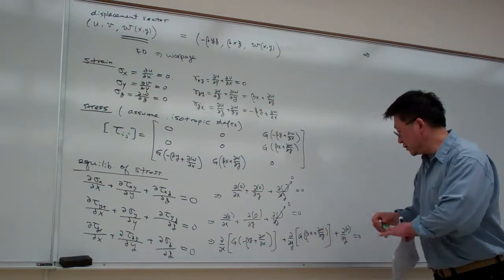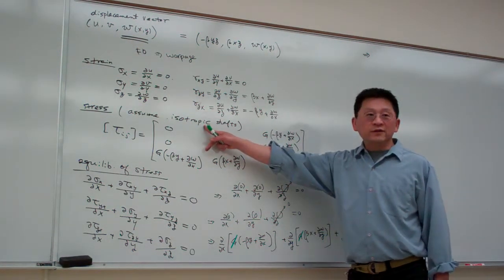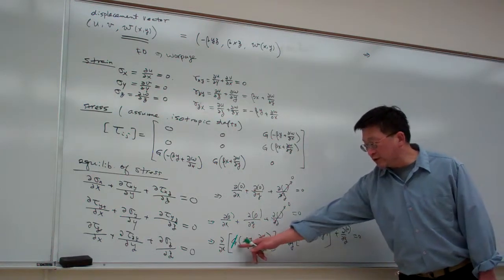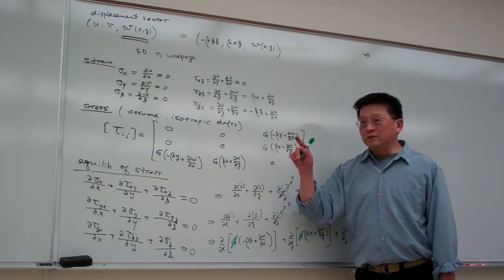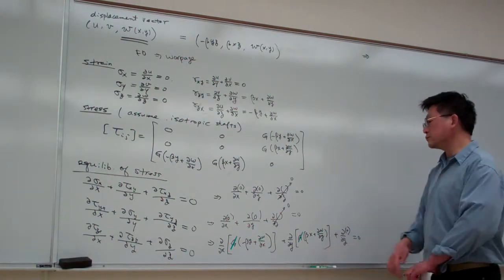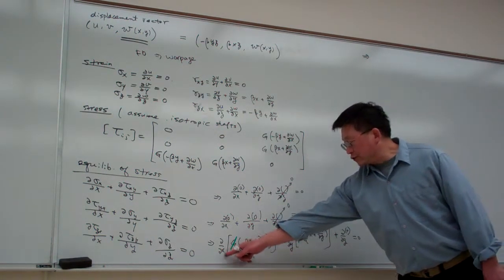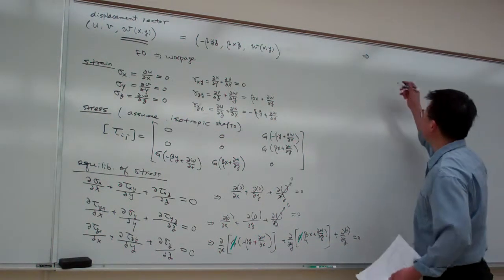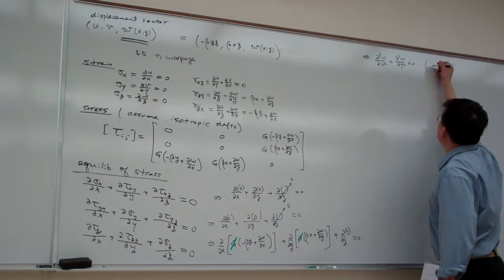So from the equilibrium equations, we come up with this equation here. For this equation, we can cancel out the G, assuming it is isotropic. If it is not isotropic, for example a general anisotropic material, then the influence happens here. For non-isotropic material, G will be a function of position, so you shouldn't drop this term. Again, for non-isotropic material, the only influence in the formulation is on the inclusion or exclusion of this term. Good? If you look at this carefully, the partial derivative of this term is gone, and the partial derivative of this term is gone, leaving only the partial w terms. So that will be equal to partial squared w over partial x squared plus partial squared w over partial y squared equal to 0.